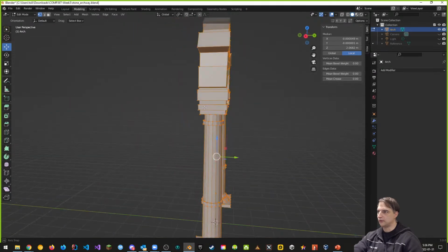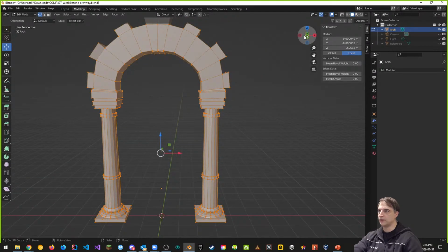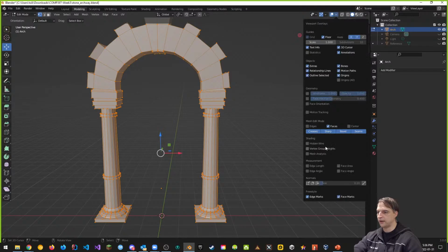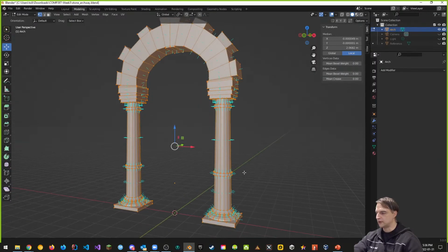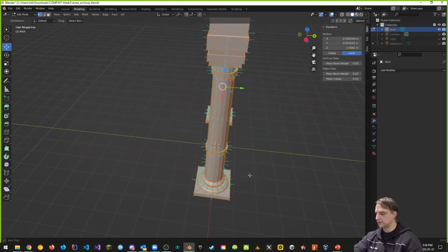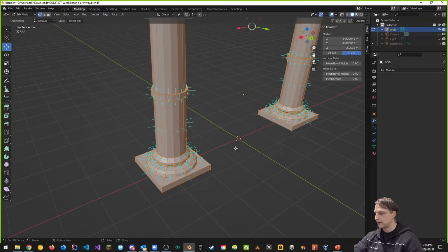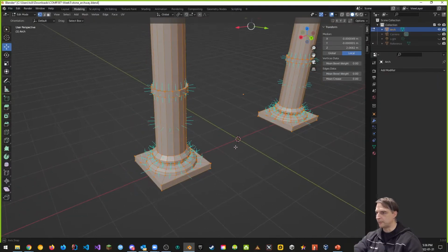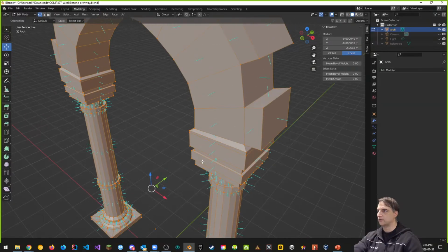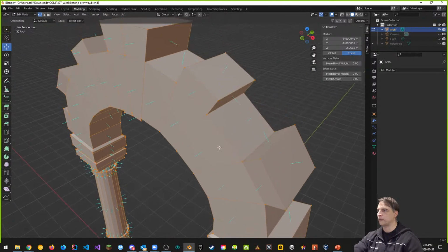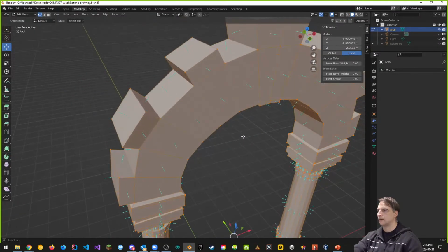Next, what we want to do is for all of this, I want to see what it looks like. Do I have everything? What do my normals look like? You can clearly see if there are issues, because this is where all the normals are. If there are any issues, they'll pop up here. You'll see normals that look like they're going inwards, or you'll be missing normals in some places.